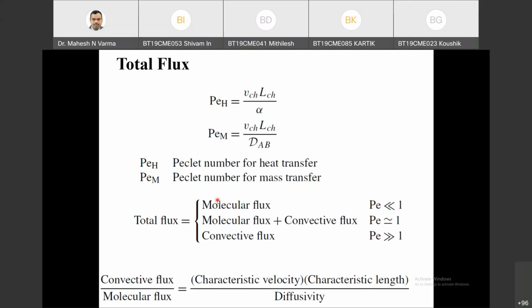The CSTR model equation is so simple, but the ideal CSTR doesn't exist in the physical world. There will be some non-ideality. To account for non-ideality, I will use the CSTR equation and at the end add some factor of safety, so whatever non-idealities are there will be accounted for.